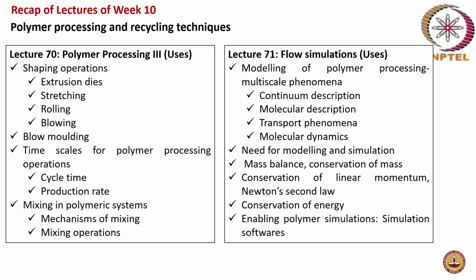These are all generic R&D packages which can be used for any system, whereas there are also processing simulators like mold flow, film blowing simulators, resin transfer molding simulators, etc. And what are the models that can be used to describe? There was discussion on the generalized Newtonian models, like power law model, Herschel-Bulkley model, and then viscoelastic models like Oldroyd, Phan-Thien Tanner, and PTT model, all discussed in this lecture.